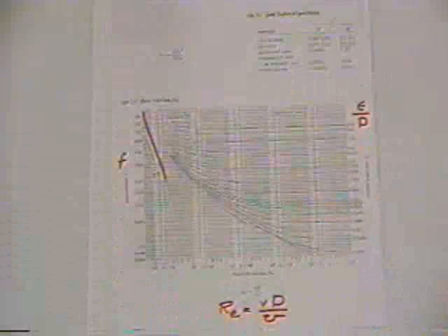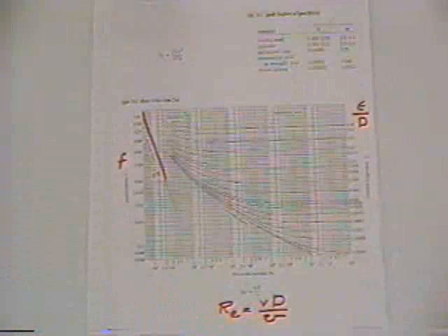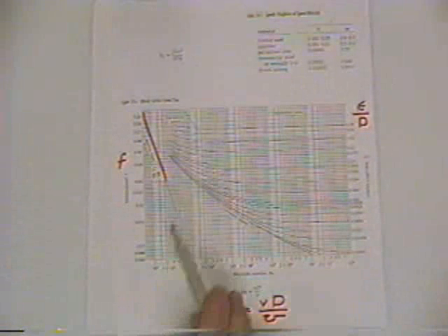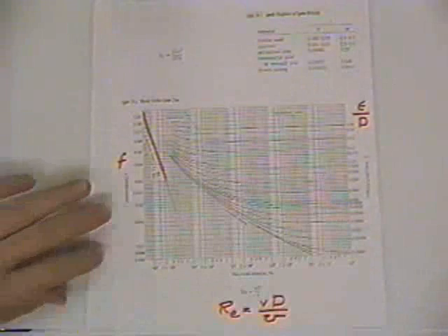And so we use the Reynolds number to differentiate between laminar and turbulent flow. If you have a small Reynolds number, down in this area, we've got a linear relationship here between Reynolds number and friction factor. And in most engineering applications, we'll have turbulent flow, so we'll be out here. And there's a certain area which we call smooth pipe flow. And this is the bottom line here.